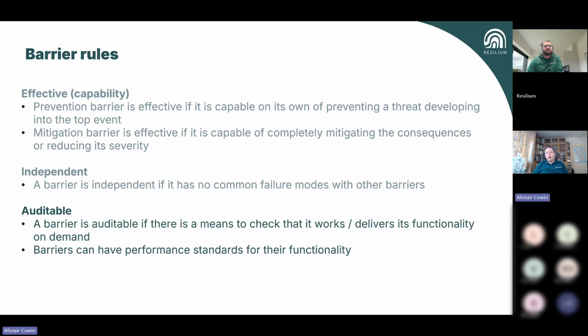It also ties into the fact that most of you have safety management systems, error management systems, failure and investigation systems that are providing evidence of barriers working, not working. And the barriers working is as important as the barriers not working, because it gives you a high degree of confidence you can rely on it. So these 3 rules, really, when you're building bow ties, have a huge impact on the quality of your bow tie and what you can get from it.